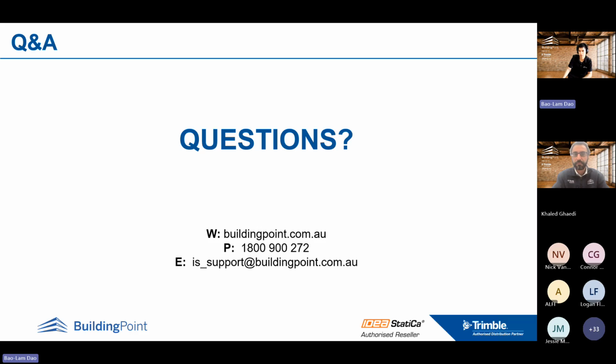Khaled, I don't know if you have any other comments to that. Yeah, you're right. But finally, if you want to consider the effect of post-tensioning, let's say internal or external, you can use Detail 2D mainly. Right now we have the feature for pre-stressing and post-tensioning in Detail 2D, so you can just consider those effects in Detail 2D.